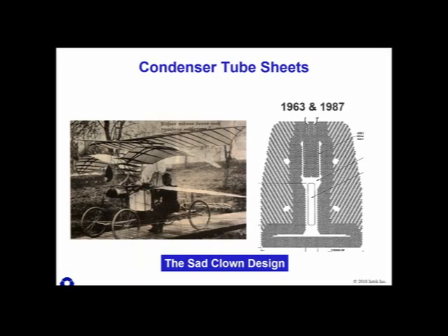This is a Foster Wheeler design. So, just a kind of a different variation of that first Ingersoll Rand tightly shrouded air cooler zone, but now this very large channel to convey the non-condensable gases up. You can see very tightly dense pack of tube bundle that's quite a distance from the air removal section.